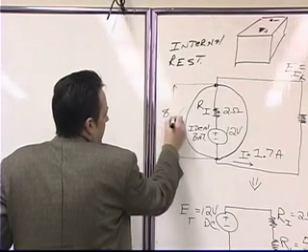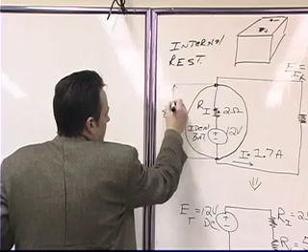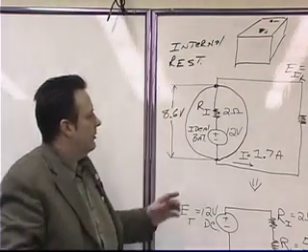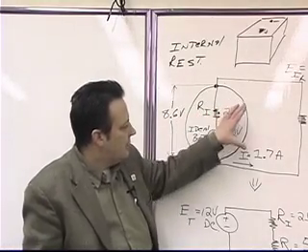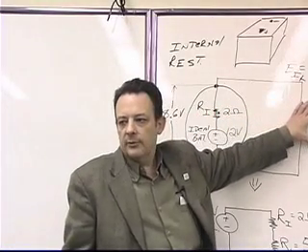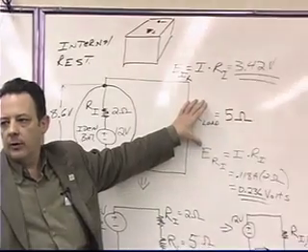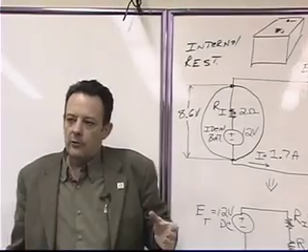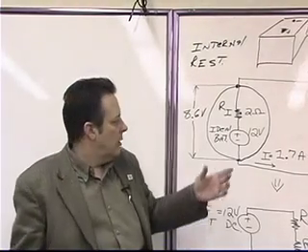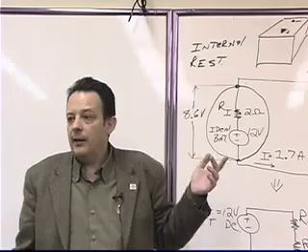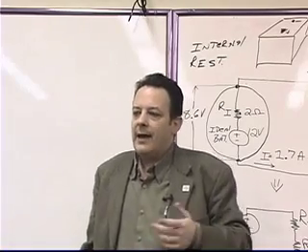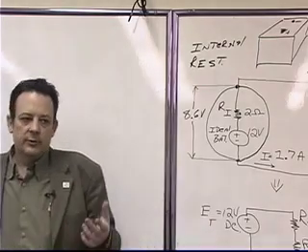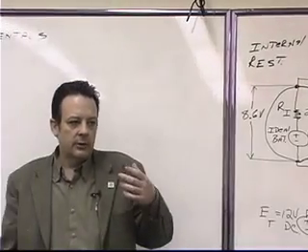So we'll say about 8.6 volts? So now you can see that the voltage that's actually usable by these loads that are all connected up in parallel with each other has dropped from almost 12 volts, 11.7 volts, all the way down to around 8.5 volts. That's the effect of having internal resistance, which is something that occurs in all circuits.